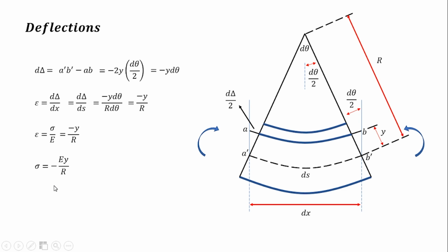So, yung stress natin in bending, that is also equal to negative M times y over I. If we want to compute the maximum bending stress, yung ginagamit natin na variable is variable c, or Mc over I. So, syempre, hindi naman tayo naka-max. So, at a certain height lang from the neutral axis yung ginamit natin na y, kaya negative My over I siya. So, equating these equations ulit, magka-cancel yung y, and we can get this equation na 1 over r is equal to M over EI. Ito yung nakita natin sa libro ng Strength of Materials.